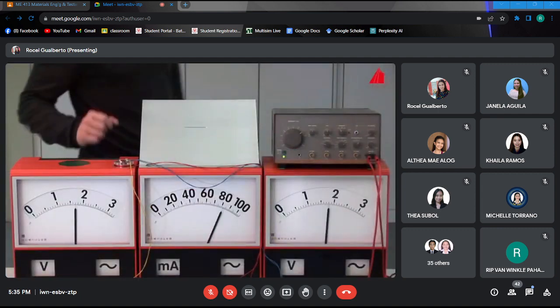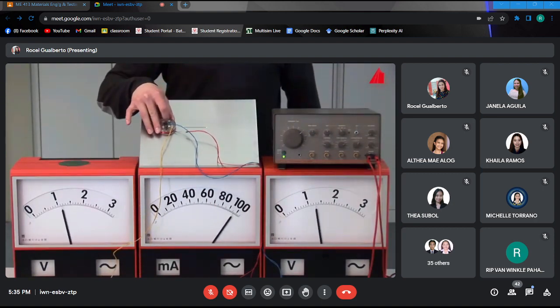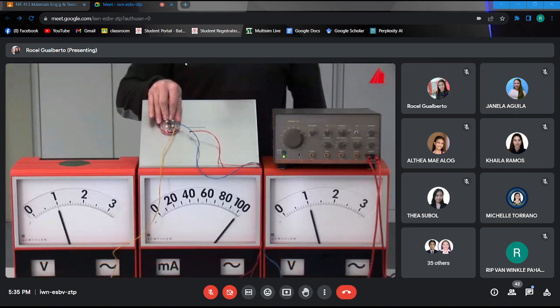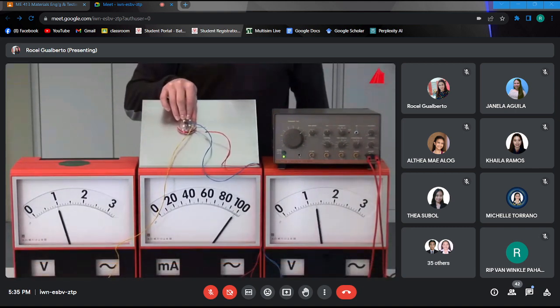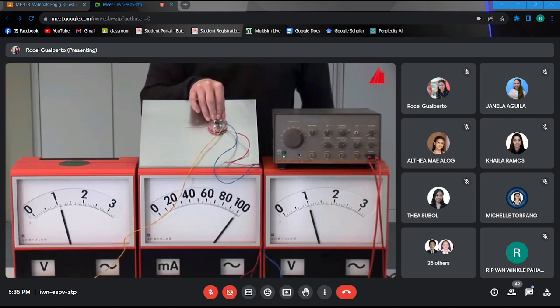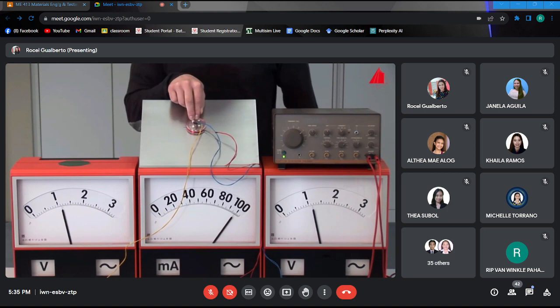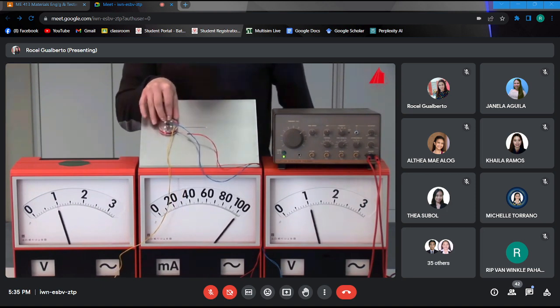When testing this coil set in the laboratory, we are initially disappointed. Firstly, already in the intact region of the sheet, a high voltage is induced in the receiver coils. This is because the receiver coils are now positioned within the excitation coil. Secondly, the saw cut is only faintly detectable.